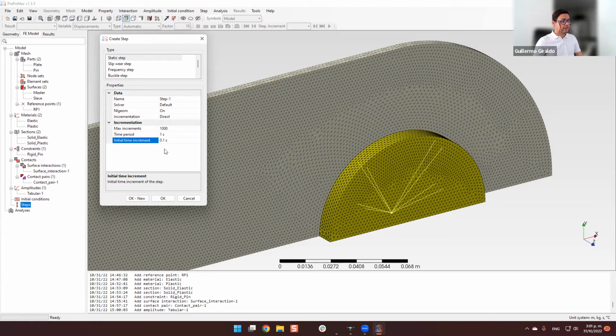So let's leave it at 10 right now, because it looks to me that this case won't have such a large deformation, and dividing in 10 steps should be enough. Otherwise, if I face issues, I can lower this value to divide 1 second into 50 or 100, even 500 steps I have seen before.